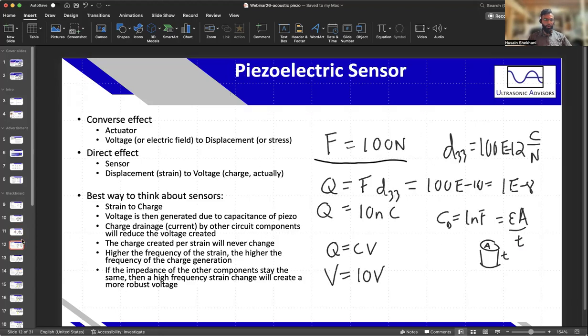So note that however you bond and you have your transducer, as long as it's not sitting with perfect stress applied and on roller supports, which don't exist in reality, you won't have these equations. But let's say we do, because the basic ideas still work in terms of calculations. So we have a force applied, 100 newtons. We have a charge coefficient. Usually the charge coefficients are between 300 to like 600 picocoulombs per newton. I'm just going to assume 100 picocoulombs per newton, just for simplicity's sake.